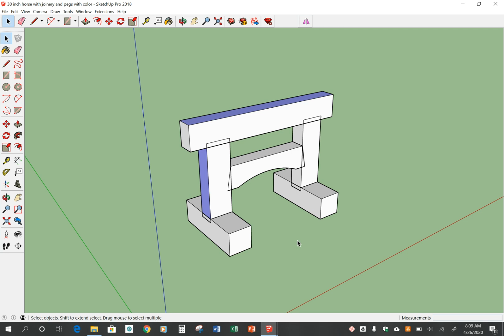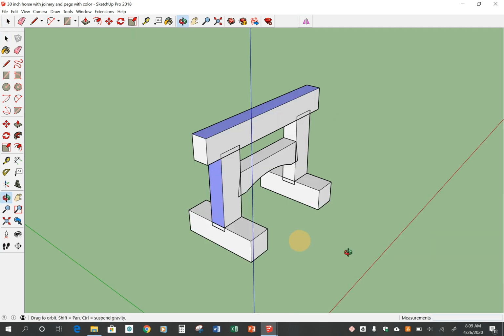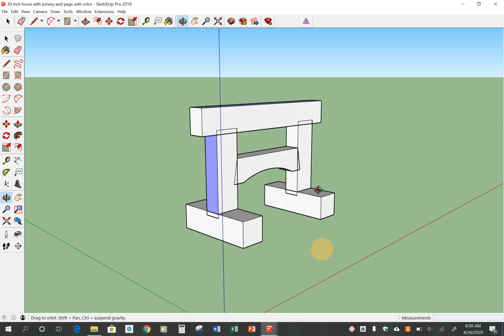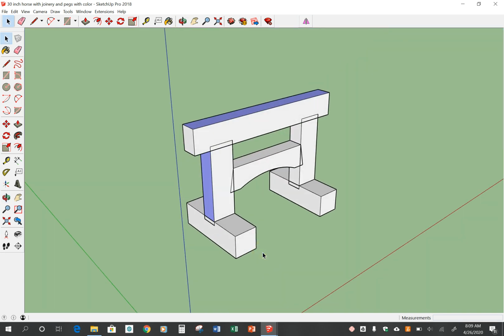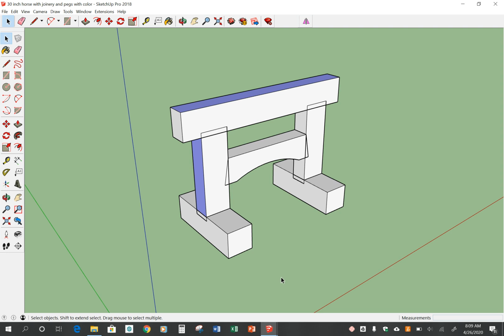So in this tutorial, we're going to learn how to make shop drawings that make the most sense, that help us do our layout accurately. So we typically use square rule layout methods, where you pull your dimensions from a reference face during layout. So a reference face would typically be a top face in a rafter or a plate. It could be a bottom face in a sill, or oftentimes an outside face in a post.